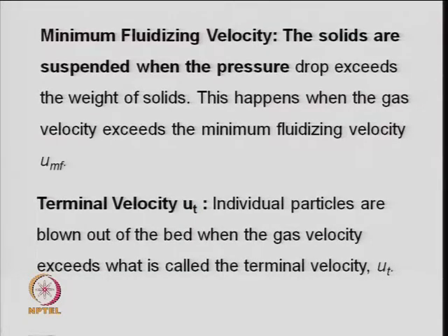This will happen when the pressure drop exceeds the weight of the solid, which happens when the gas velocity exceeds the minimum fluidization velocity. So, through packed bed experiments or fluidization experiments, one needs to calculate the minimum fluidization velocity required for the given size particles in a given column diameter, and then the other things.